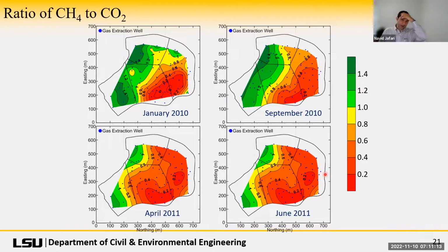What has been a better signal spatially is doing some geostatistics with the methane to carbon dioxide ratio. When you stitch those together using semi-variograms, they actually come out quite beautiful, and you can color code them. The red here represents no methanogenesis, which is pretty much 0.4 or below. Then, when I think of a stoplight, you have the yellow or orange from about 0.6 to 1. That's the transition as it's going down. And then anything above 1 is healthy, or we have the green light.